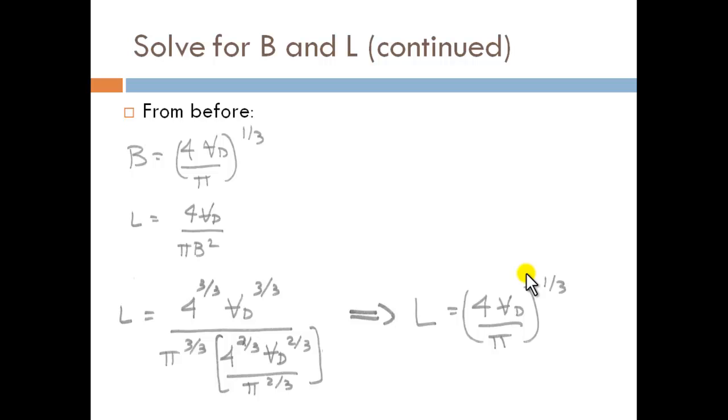There are a lot of nonlinear effects inside the combustion process and inside the engine combustion chamber, and so in modern engines you don't necessarily have a one-to-one bore to stroke ratio. In fact, that's why I used B and L, because those are the standard variables for bore and stroke respectively. You see that because of combustion effects, emissions effects, fluid dynamics inside the cylinder, and different combustion speeds within the combustion chamber at different times, you don't necessarily get a one-to-one bore to stroke ratio, but it's close.